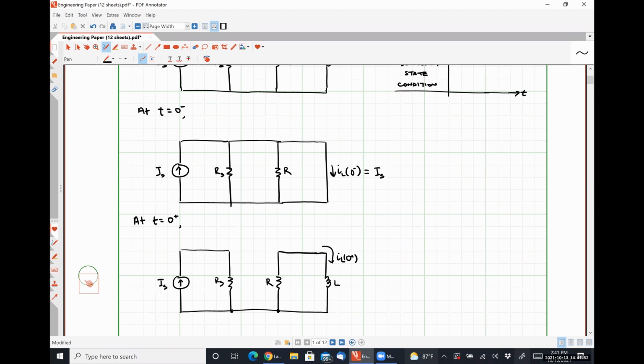And that bottom line there is all connected, right? So this is what it looks like immediately after our switch has opened up. Now I want to be clear here. I cannot represent my inductor as a short circuit anymore because we no longer have a DC circuit. Now this looks like it's going to be a DC circuit, and we're absolutely going to perform DC circuit analysis on it to an extent. But because we have moved from that DC steady state into a transient condition, we can't simply brush it away and say it's a wire anymore. It's now actually behaving like a specific circuit component, okay?